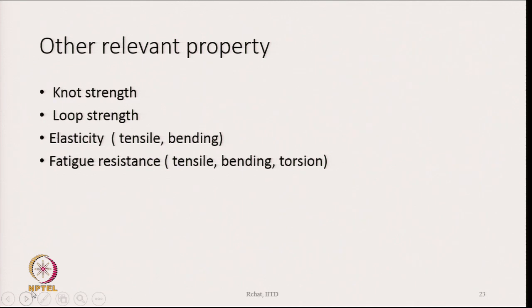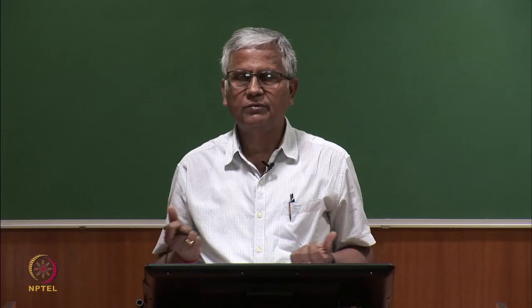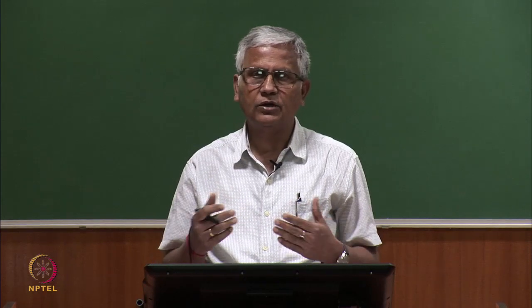Other relevant properties of the fibers which will be important are knot strength of the fiber, loop strength, elasticity, that is on tensile and bending, that is how much is the recovery property. If I subject a fiber to tensile deformations, how much does it recover, or if I subject it to bending deformations, how much is the recovery.